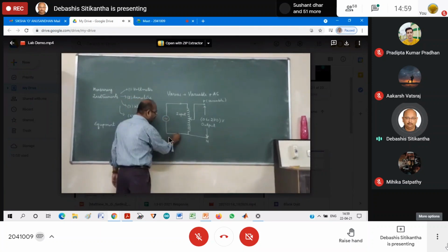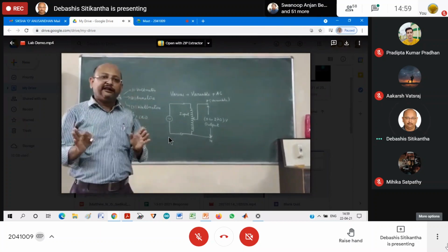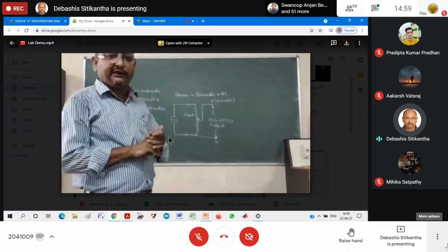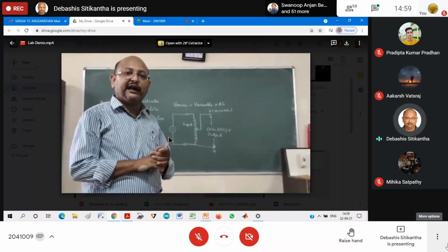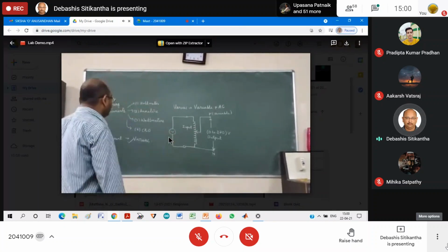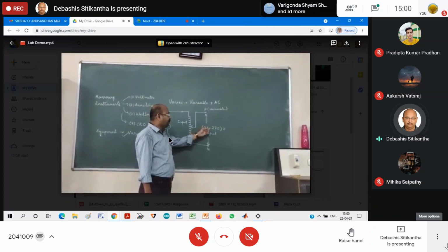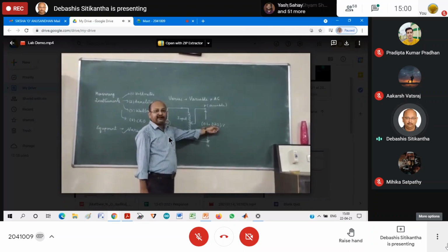Please remember, the variac is only used for changing the level of AC voltage. That means only AC voltage can be altered. From a 230 volt AC supply input, you can draw voltage from 0 to 270 volt AC.